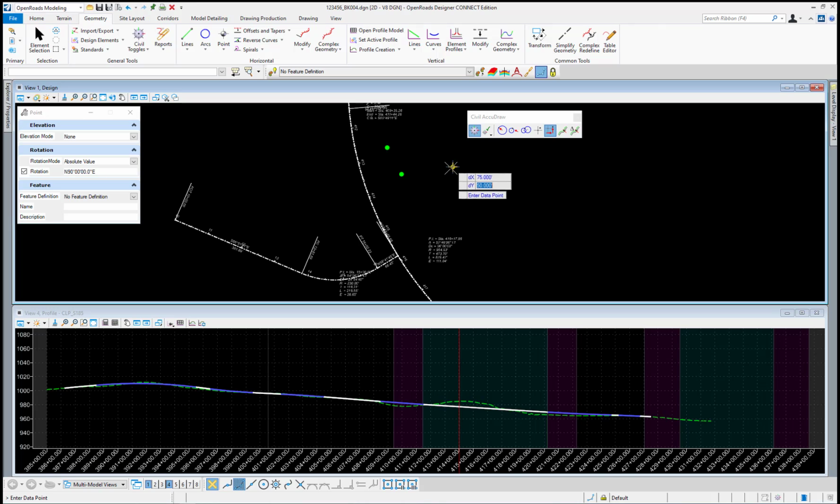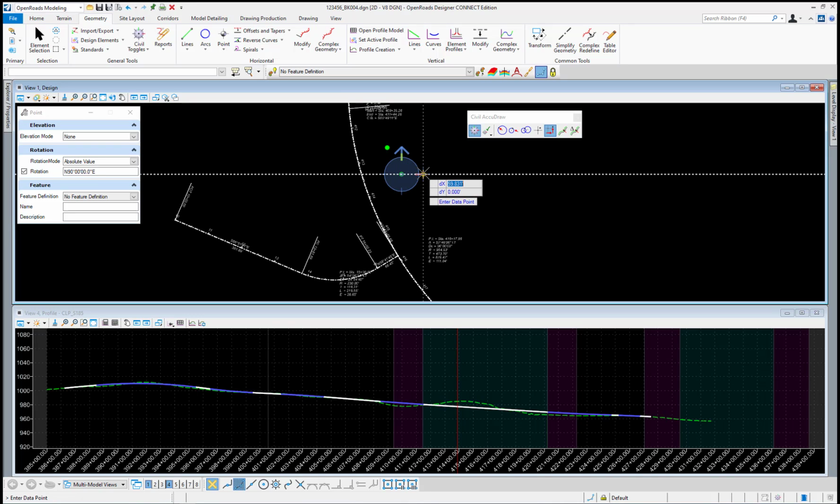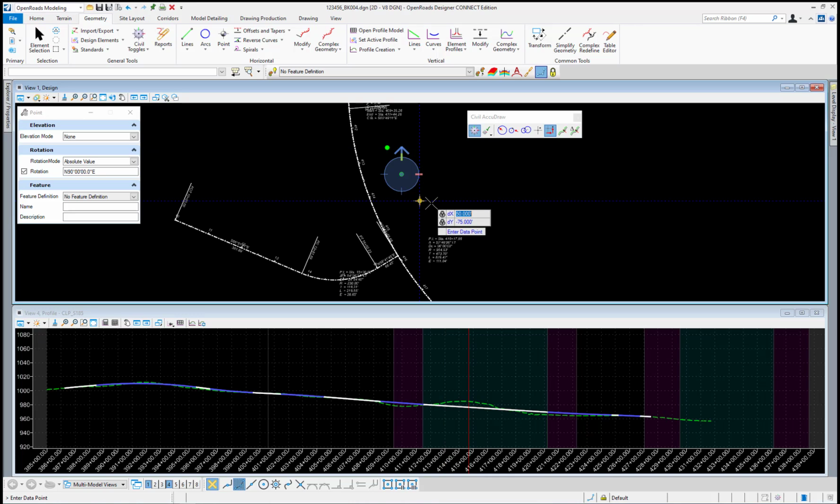And I want it to come from the last point that I placed, but I can also select another origin point by pressing the O button on my keyboard, and then I'm going to select my point to give it the origin value. Once I've done that, I'll enter the values again here, and these should lock this time when I press the Enter key. And a negative value would go to the left, obviously. Oh, I actually wanted it to be negative 75. So now I have a new point here, a data point to accept it, and a new value is placed.